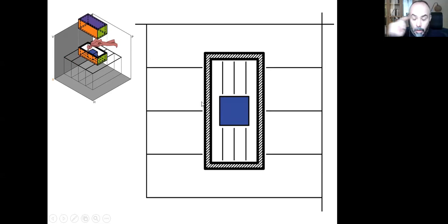I can use like 0.5 millimeters for the gaps between them, and I can create these lines by using my set square, the 45 degree set square here, and I can use a little thin lines, but they are still black.